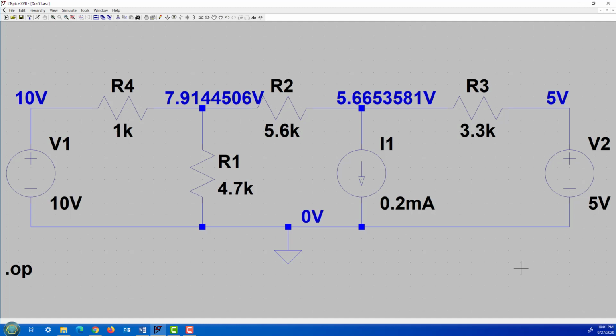Now, what else can we answer from the circuit? Number one, the power absorbed and or power dissipated means the same thing for the resistors. Take your cursor, hover over it, read the lower left side. Dissipation says, for this one, 4.349 whatever. Okay, it's about 4.35 milliwatts, right? So it's 4.35 times 10 to the minus 3 watts, okay?